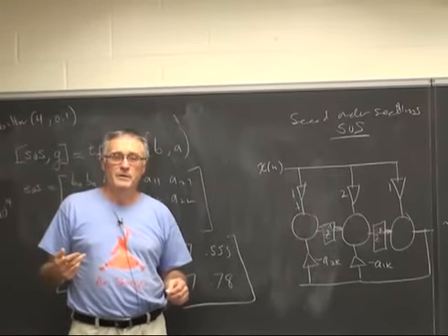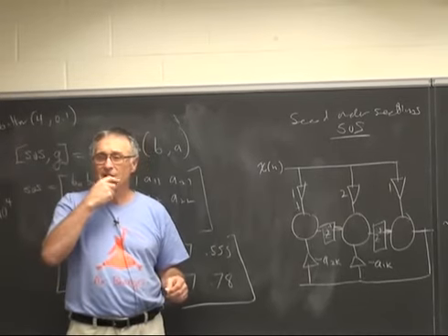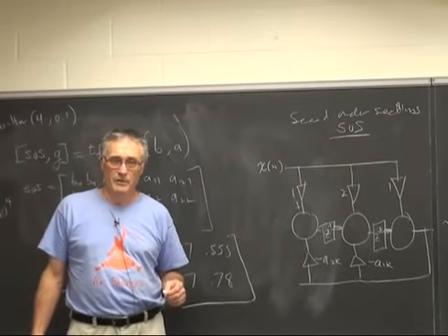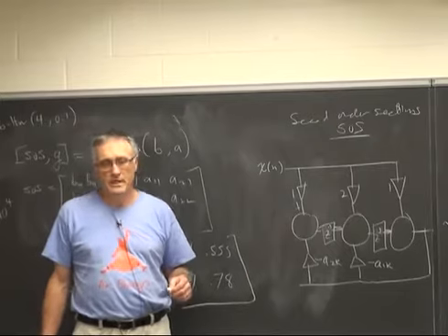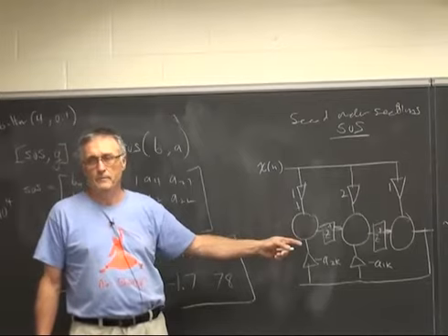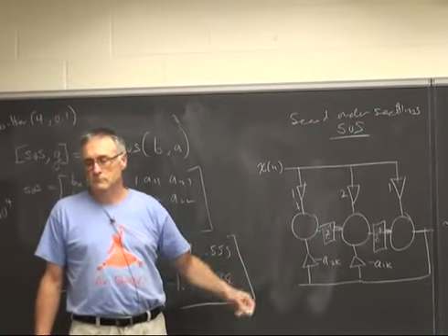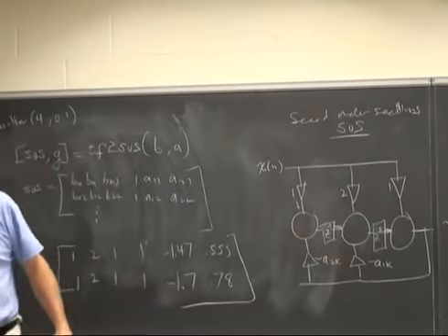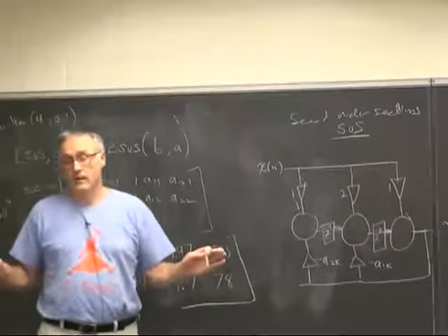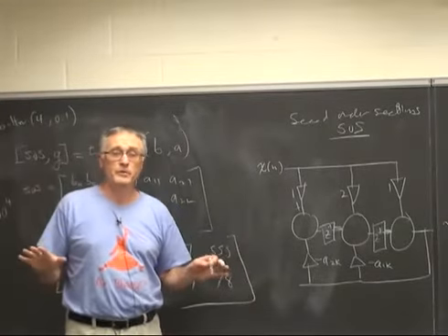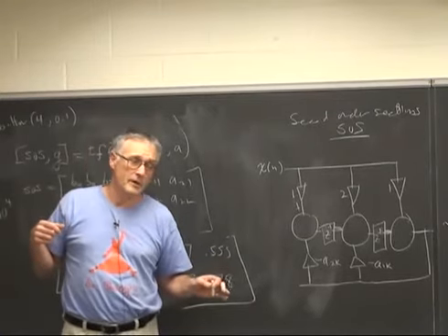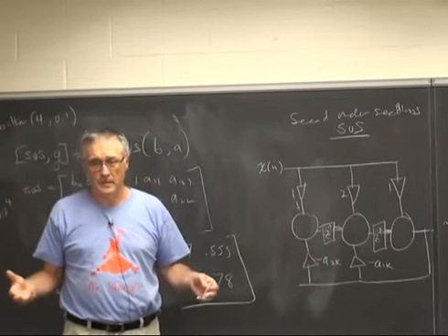You can implement about 70 multipliers in 9-bit and about 35 floating point multipliers in 18-bit floating point. So if you were going to do second order sections in hardware, it would probably be best to do them in 18-bit floating point. For this lab, you're not using hardware. You're using software running on a CPU. And I'm only asking you to implement second order filters, and so there's no particular reason to use a second order section.